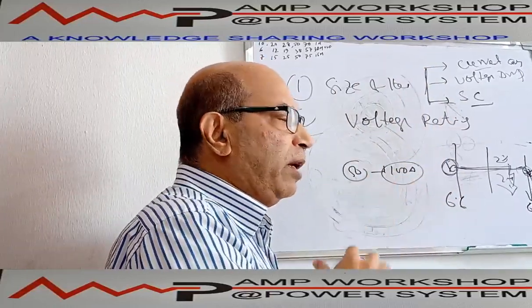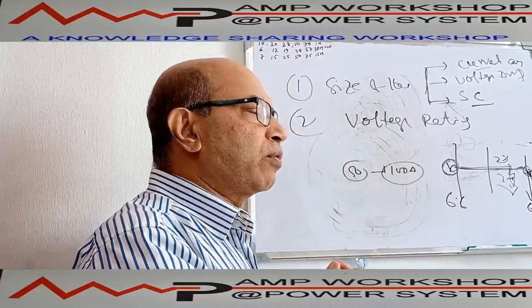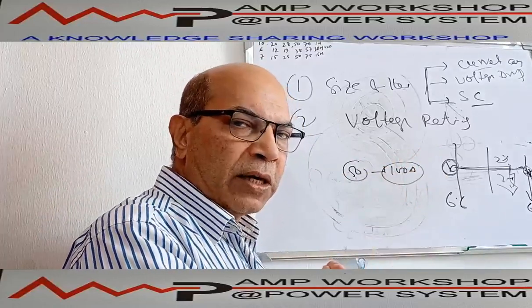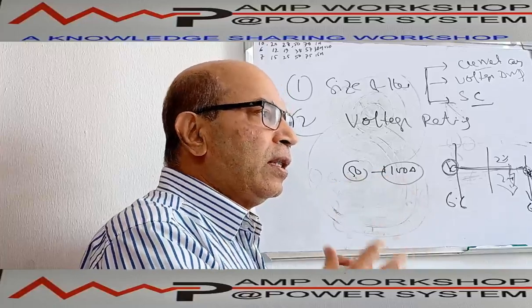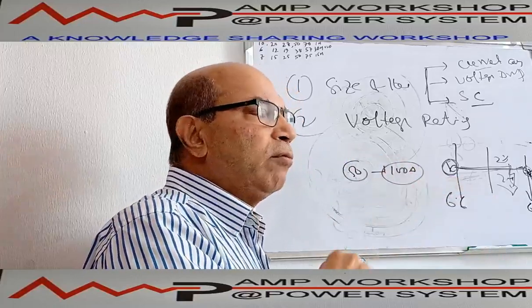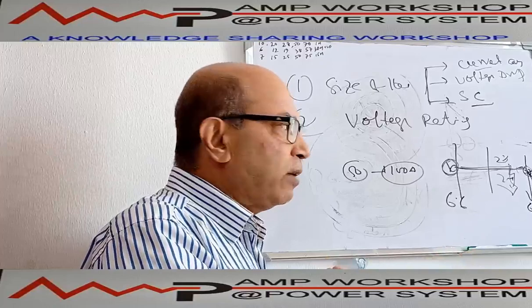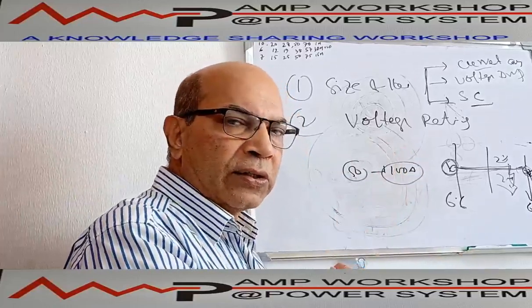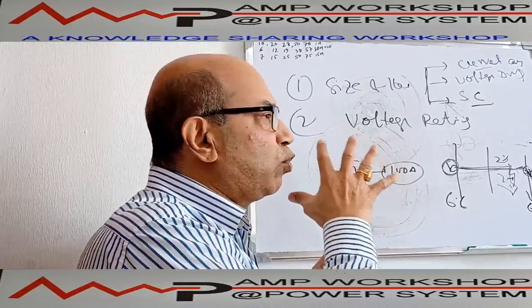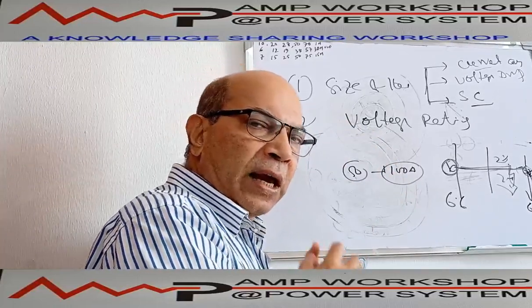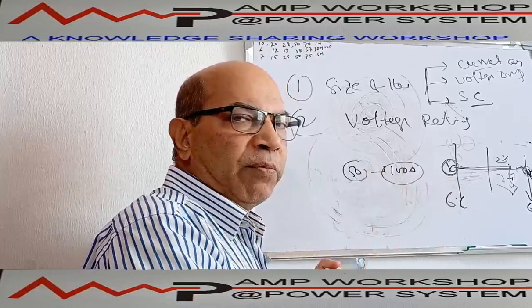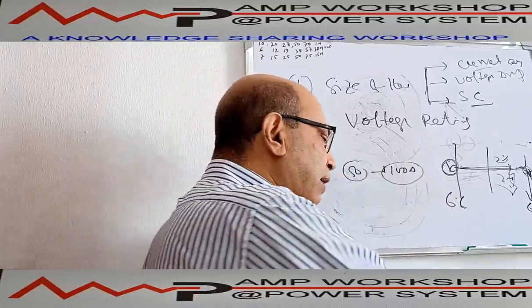Now the second part will be what grade of voltage we have to use. For that, there is a voltage grade of the cable. There are three different grades available. We'll discuss this: continuous voltage, and then we have a short time voltage rating of the cable as well. So these are the two main calculations required to decide the cable sizing from the system point of view or from the design detail engineering point of view.